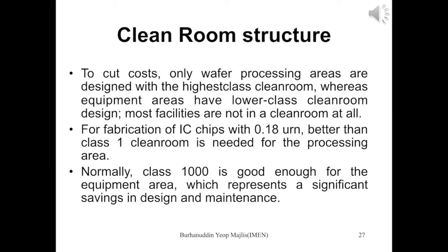So the body of the equipment we can have in the not very clean area, but the process area has to be very, very clean. So it has to be class 1 or class 10, for example. But class 1000 can be for the equipment or also for service.